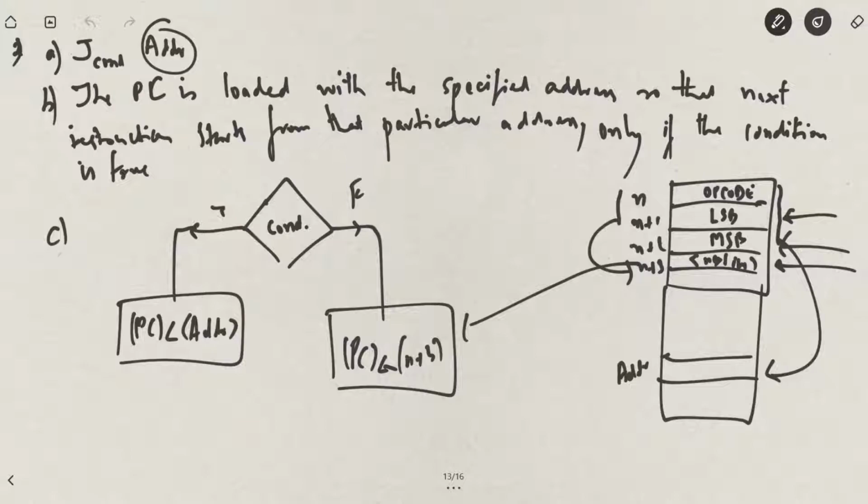So what does jump do? Once this instruction is executed, if we find out that the condition is true, or even with the normal jump instruction, the program will jump to this address location and start instructions from there. But with call instruction, it jumps to this location but also saves the return address.